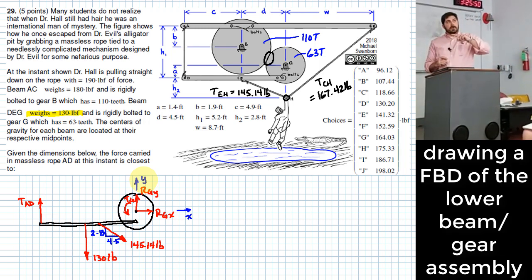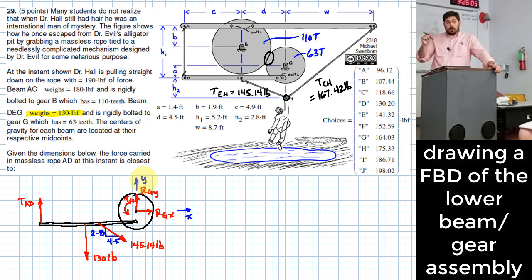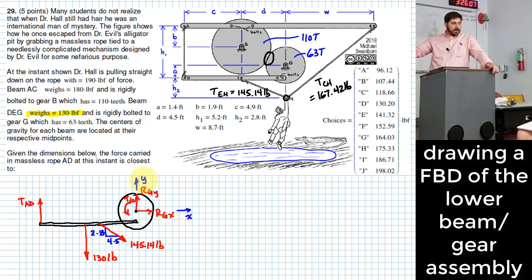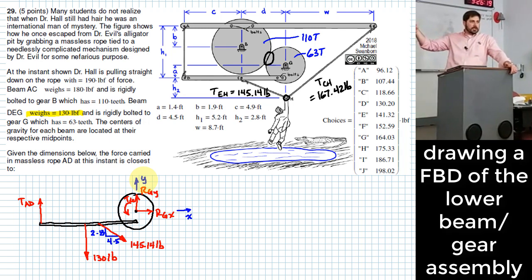We're ultimately going to write some equilibrium equations out of this body, so think about how I could eliminate some things that I don't know out of my resulting equations. You want to eliminate the things you don't know that you don't care about, right? You don't necessarily want to eliminate TAD, because that's actually something you want to find. What might we want to eliminate instead?